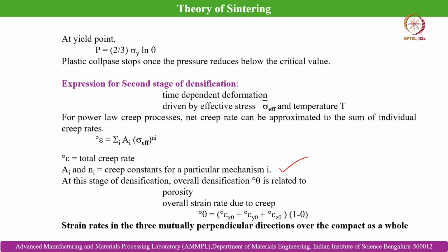So, the second stage, which is a thermally activated stage, is where we generally do not apply pressure. We are talking about the traditional sintering process here, where the pressurization and the thermally activated stages are separated and sequential, that means one gets activated after the other one. So, we are talking about the conventional techniques.